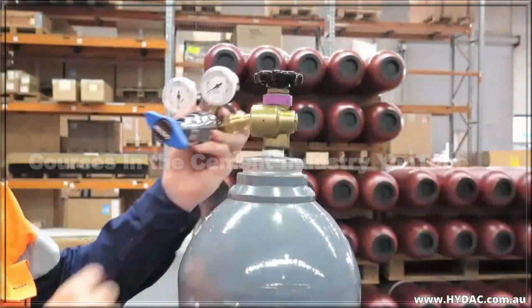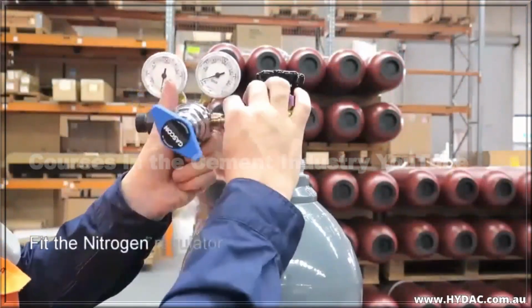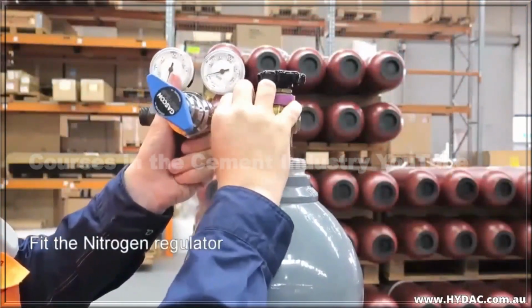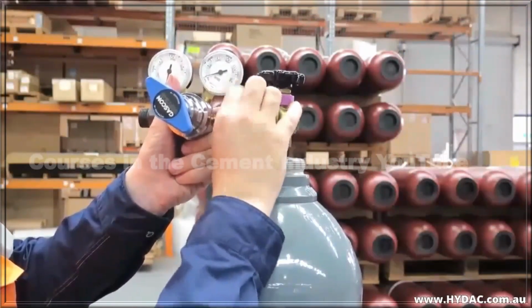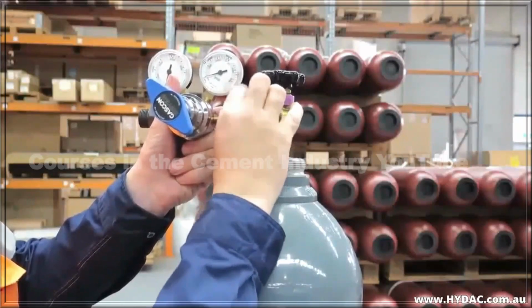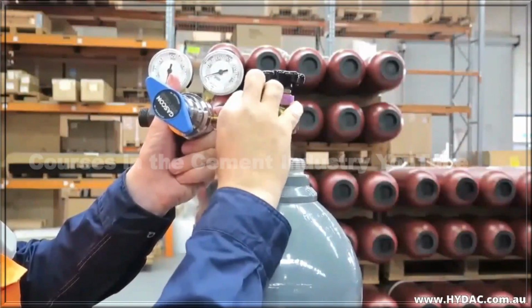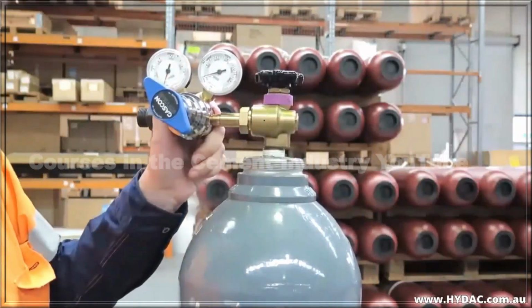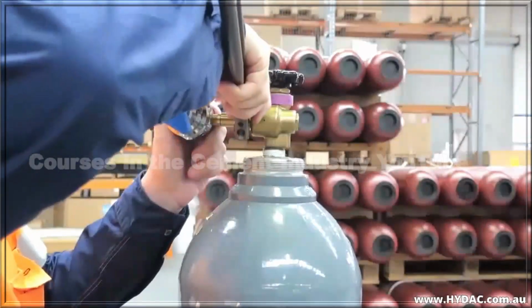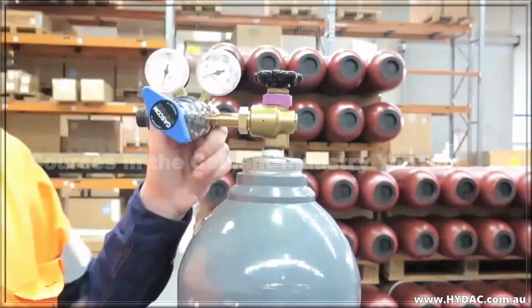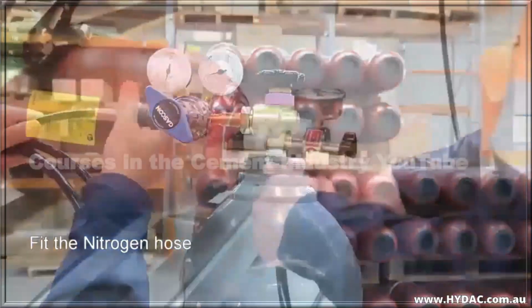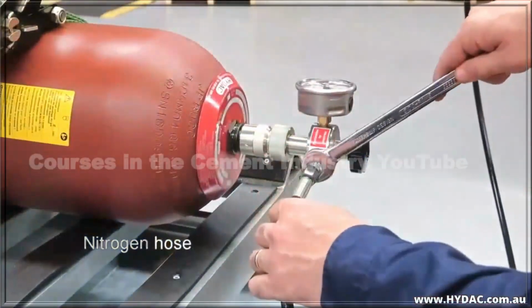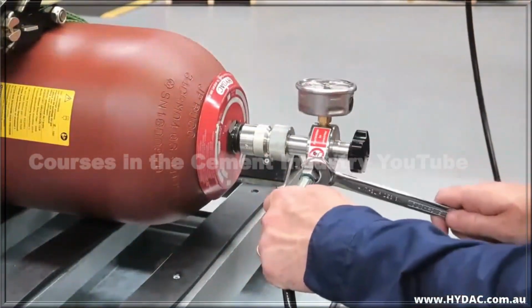Before connecting a nitrogen regulator to a nitrogen bottle, ensure that the regulator will be closed by backing the pressure setting down, winding the adjustment counterclockwise. Make sure that the threads and seats are clean, and connect the nitrogen regulator to a bottle of industrial-grade nitrogen. Connect the hose in between the regulator and the universal test and charge head. Open the isolation valve of the gas bottle.